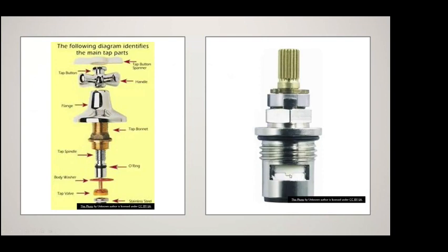This one here has got a mini ceramic cartridge for an individual tap, so it basically replaces that with a mini ceramic cartridge. They're the two bits of ceramic in there, and they basically overlap like a shower mixer to let water through when it's in a certain position. So it's basically about a 90-degree turn or something from fully open to fully closed. It's this one you turn the handle several times.